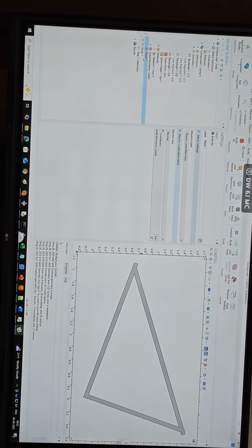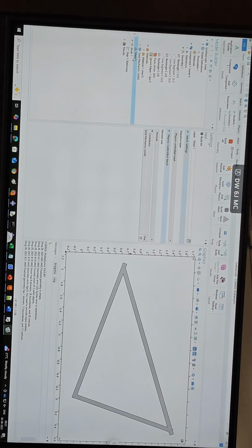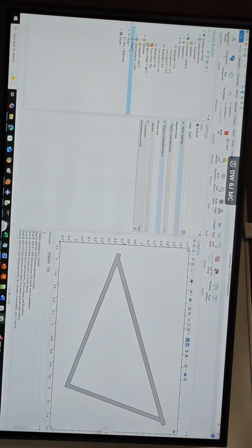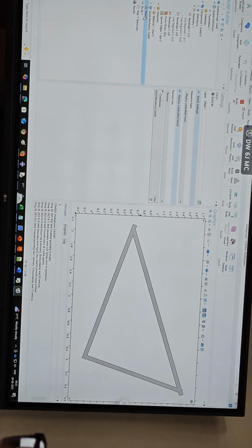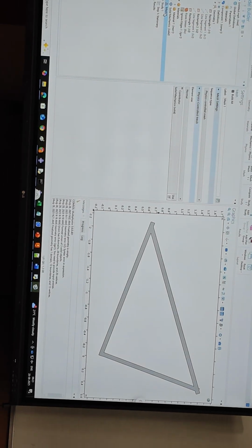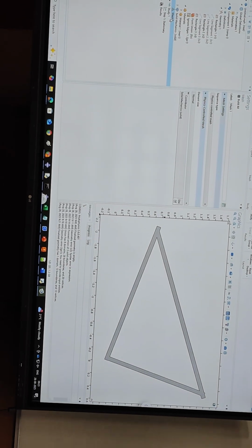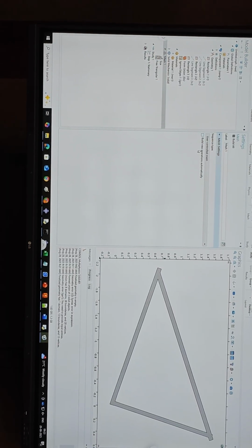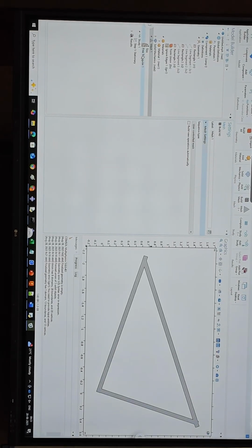Now we come to the mesh. So generally people love using a physics control mesh because that's the easiest thing to do. But I don't recommend people to use physics control mesh. They really can't control, in some sense, partitioning strategies from using a physics control mesh. So what I'll do is I'll just jump to user control because it's much more efficient, and for the further use of Comsol ahead in this course, you will be using a user control mesh. So we'll go to user control mesh.